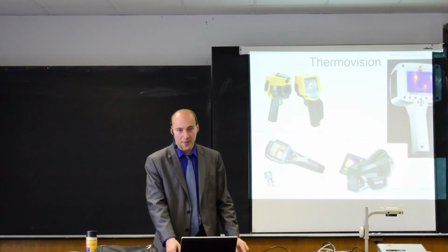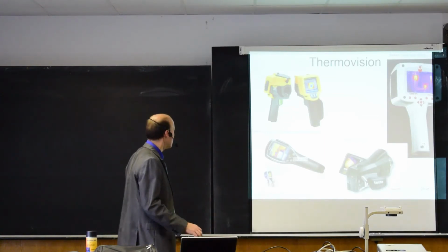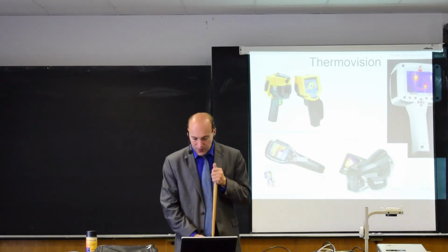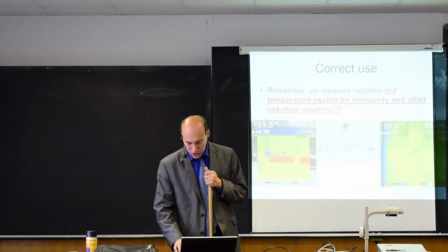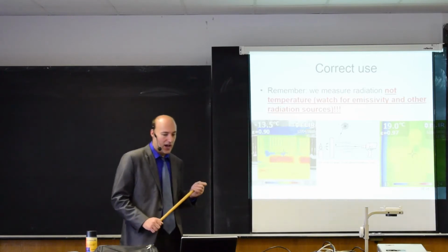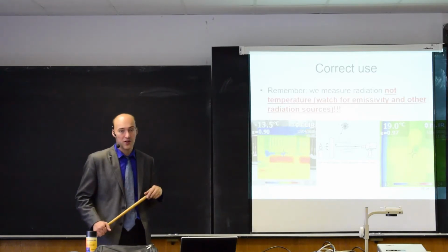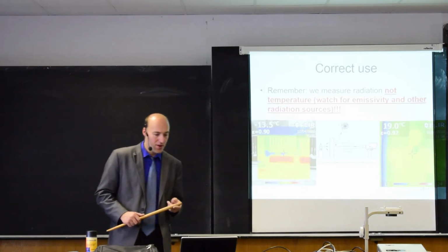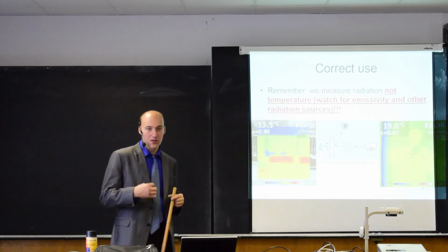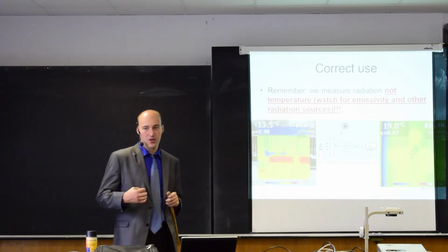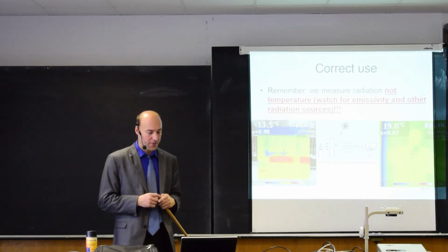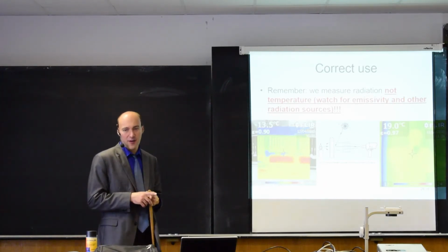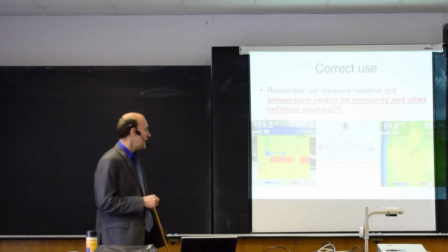The thermal camera, so you have a chance to play with that. I'd like to show you the correct way how to work with a thermal camera. We always need to remember that we are not measuring temperature, but we are measuring radiation. So first of all, we need to set emissivity correctly.